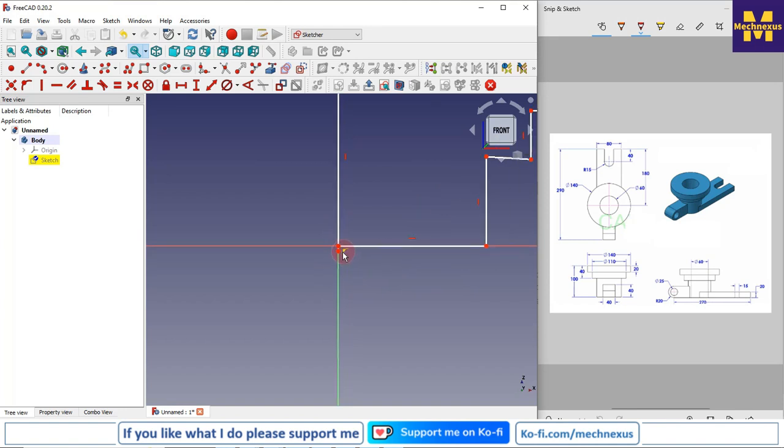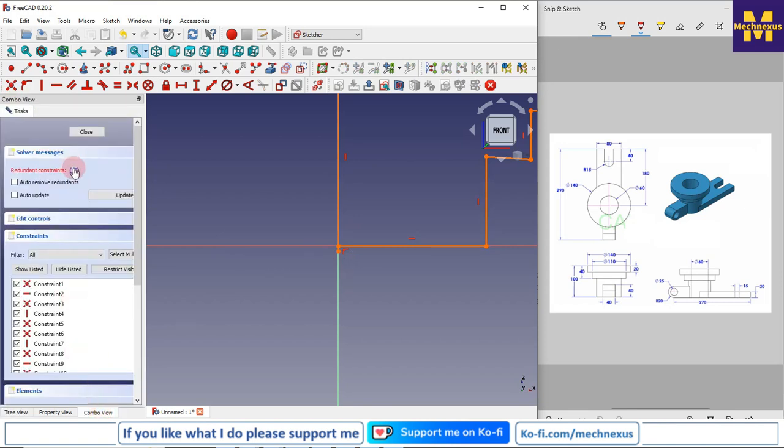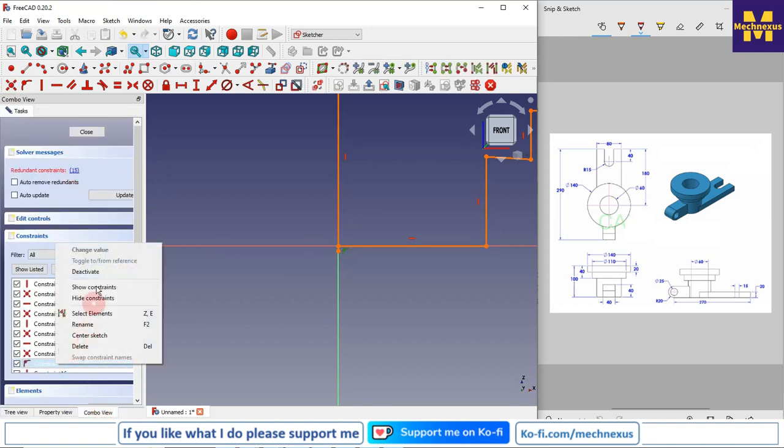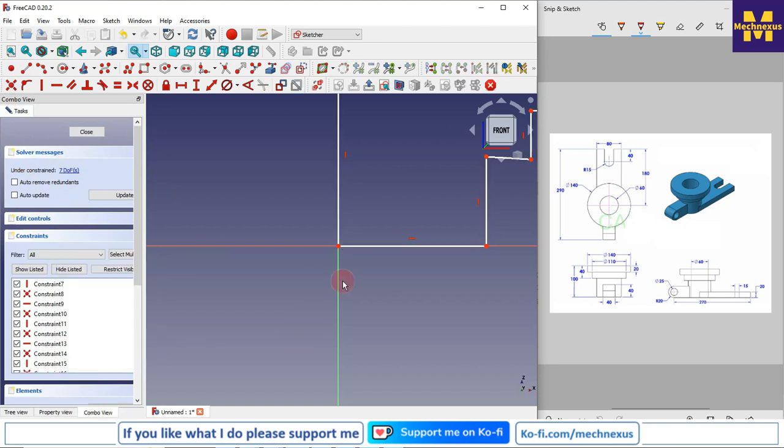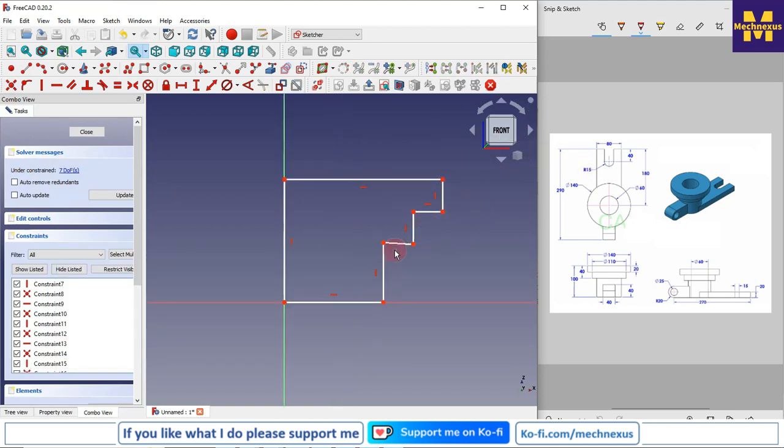Now here I will merge it. For the conflict I will select and delete it. Now I will make this line horizontal. Now we will read the dimensions of our revolve. Outer is 140, so this will be 70.